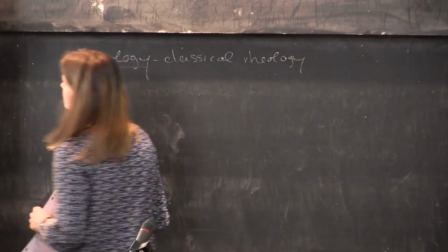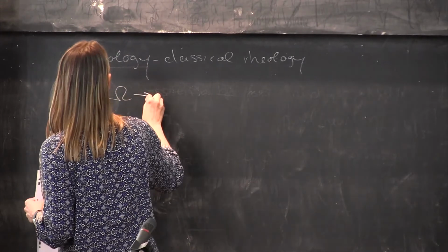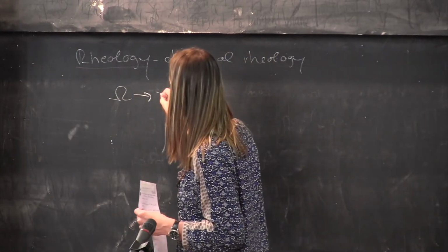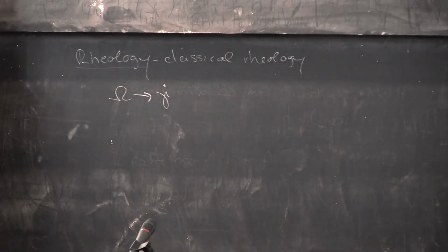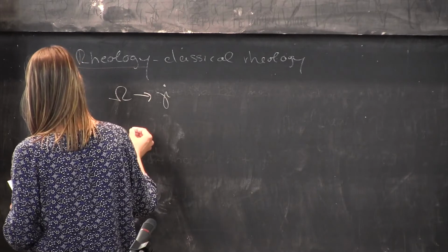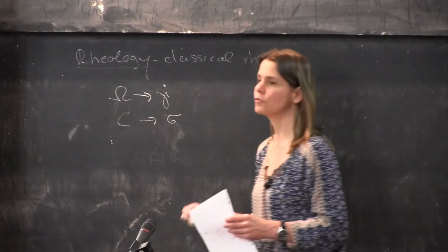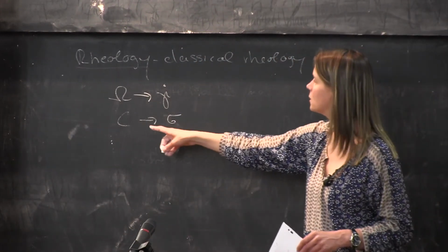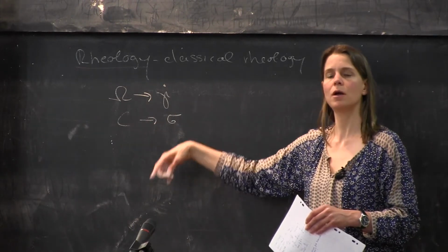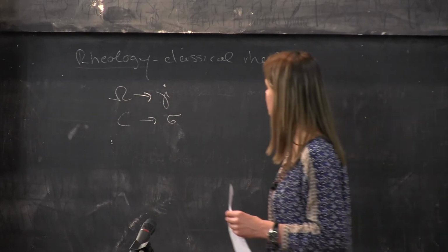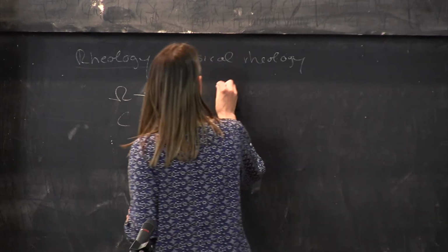What you typically do is use a rheometer, which has things that turn. You have a certain rotation rate, and you have to convert it into a shear rate. Then you measure the couple on your geometry, which I call the torque, C, and this has to be related to the stress. Rheometers can either impose the rotation rate and measure the torque, or impose the torque and measure the rotation rate. Both exist. This link is typically done by the geometry, and I will write this down for the Couette geometry.